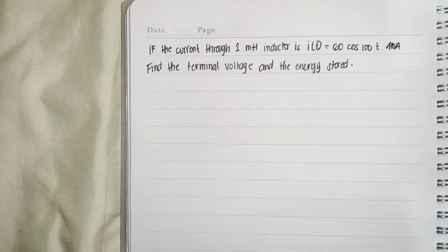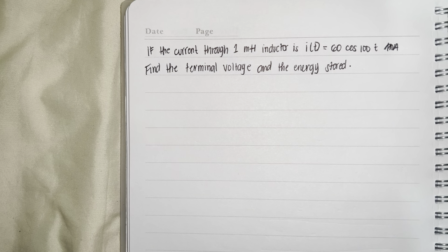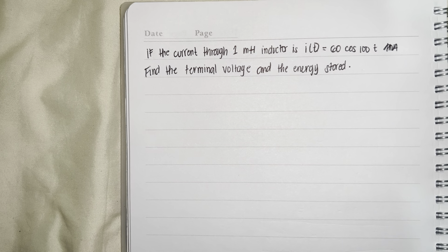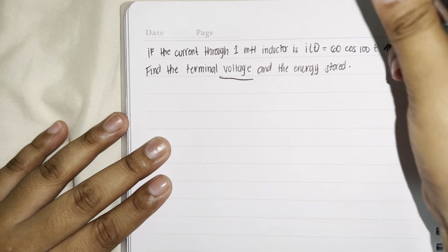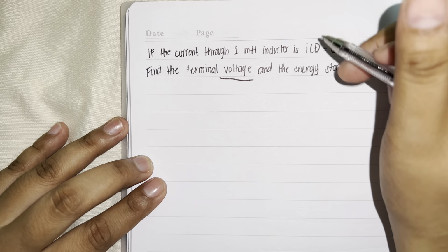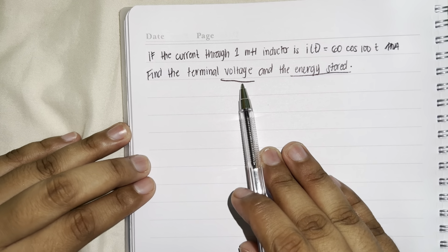This is one of the practice problems of an inductor. If the current through a 1 millihenry inductor is i(t) equal to 60 cosine 100t milliampere, find the terminal voltage and the energy. So in this problem, we're going to find the voltage and the energy stored. For the voltage, we will be using the formula